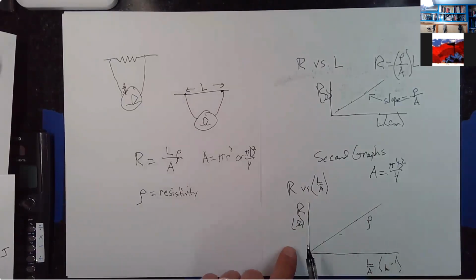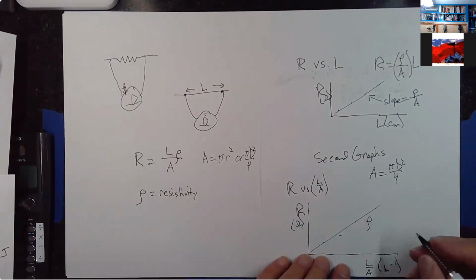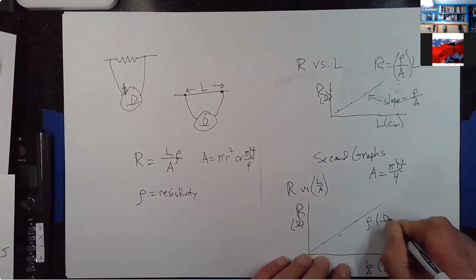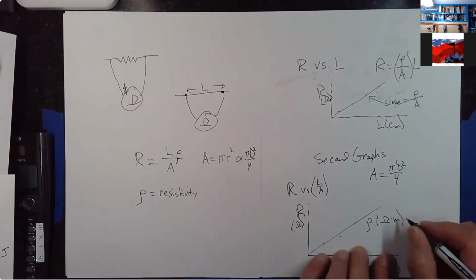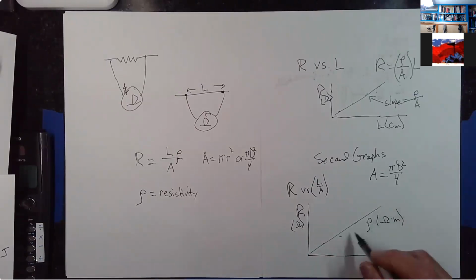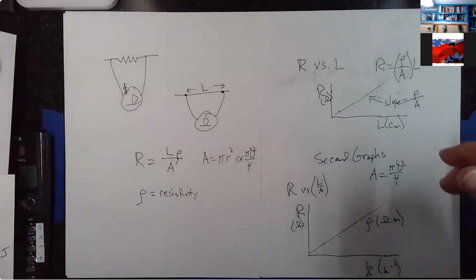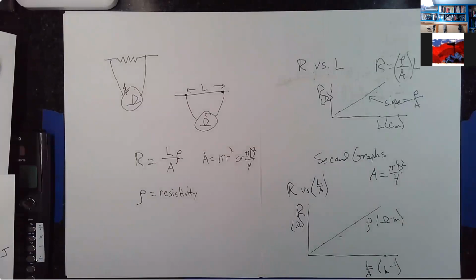It'll have units of ohm meters or ohm centimeters, and it's your choice. Sometimes you'll see the resistivity on the internet or in whatever table you find in ohm meters, and sometimes in ohm centimeters. Oftentimes they'll just ignore the factor of times 10 to the minus whatever that shows up, and that'll be at the top of the table, so you need to watch out for that.